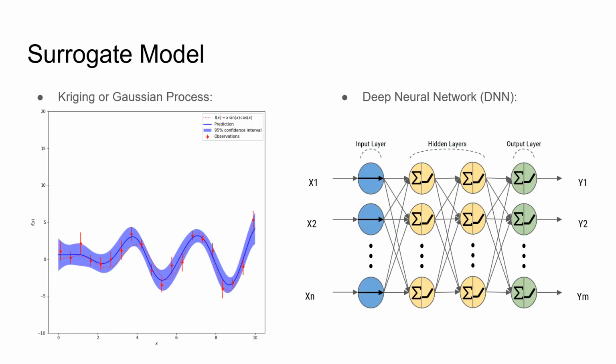With all input and output parameters defined, two different surrogate model methodologies are used. First, a Gaussian process or Kriging model is trained to predict the maximum load for both cases. A Gaussian process was defined for each output value. Second, a deep neural network is trained to predict all loads using one network. In the steady case, 1025 samples are used to train both models, and in the unsteady case, only 715 samples are used.